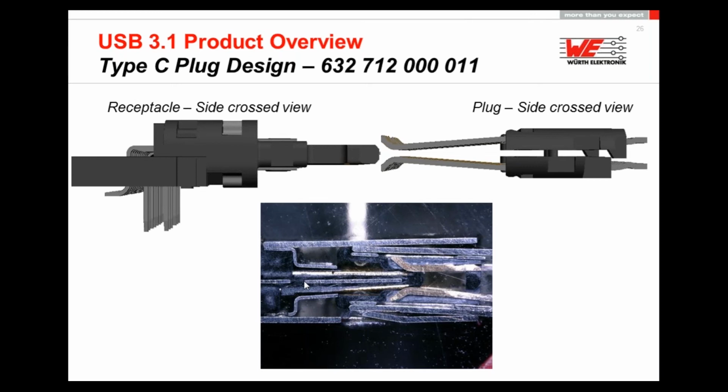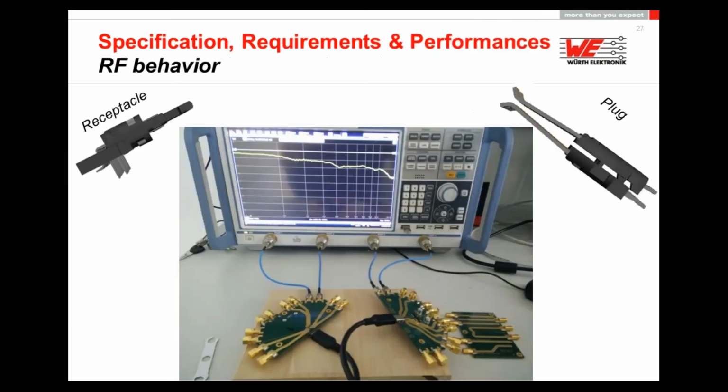The next point we can really observe in this picture, and that's very important, is a grounding layer between the row A and row B. We all know that not connected or not used pins work like an antenna, and they can transfer and also receive signals, so that would destroy our whole speed if we would lose some information there. So the grounding layer is really important in that context.